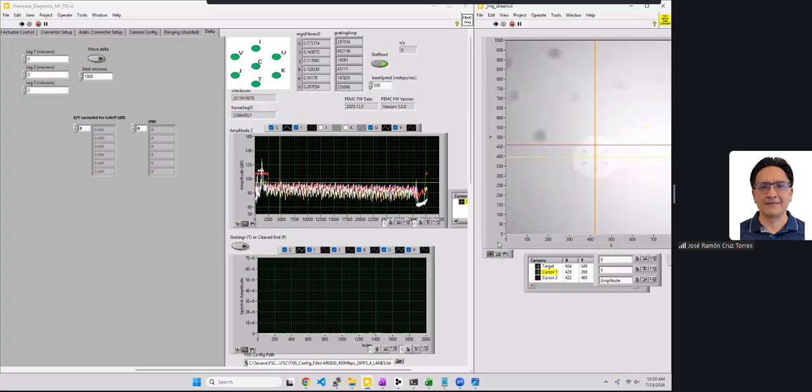Like Chuck said, the main symptom of clocking, if you disregard the image and just look at the gratings, is that your center core is really well aligned, but all your others are weak. However, that could also be magnification, because we're magnifying and then focusing the image back. If you have a magnification discrepancy, you could be correctly clocked, but all your outer cores are way out there, and you still wouldn't get coupling. So it would show up in a very similar way to clocking.